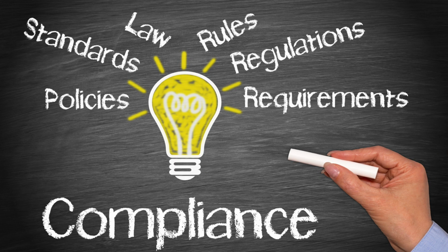Our discussion will cover adherence to statutory and regulatory standards, highlighting how these products can assist in fulfilling the criteria outlined in Building Regulations 2010, British Standards, and the inclusion of fire protection in alignment with Approved Document Part B, noting that roller shutters fall into the category of doors, and as such do not fall within the remit of Part B, Regulation 7, Paragraph 2. See gov.uk Part B for full details.